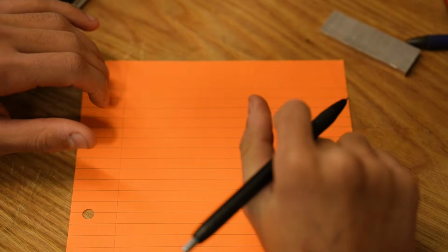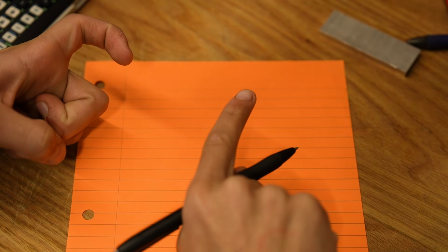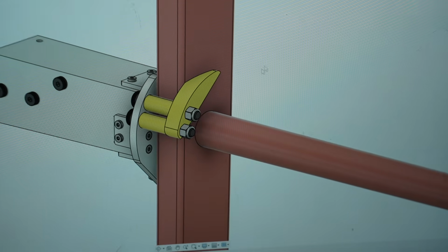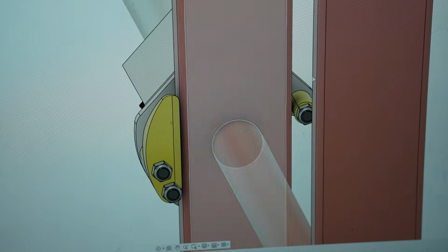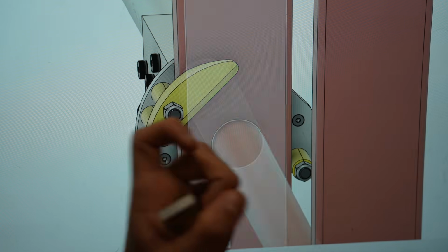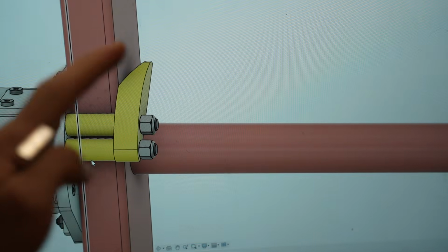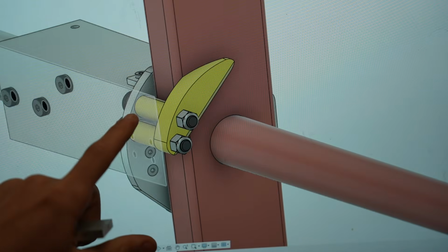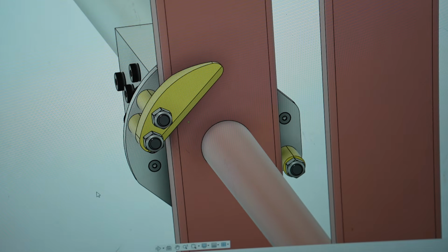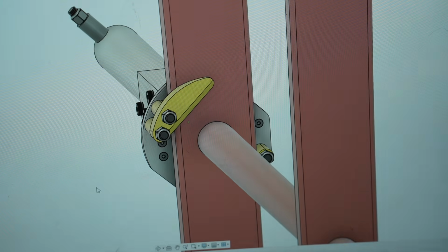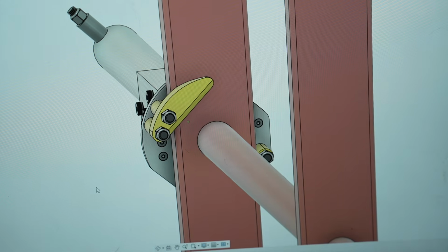Now the last elements we're going to look at are the hook and the nubbin, I think we're calling it. We can look at the CAD real quick. I'm gonna stop it there. Battery's about to die. Great. These hook and nub onto the tower here. So as this rotates, this locks in and prevents rotation off the tower, and then this bolt and the nub allow the robot to torque against the tower. So those are the load cases there.